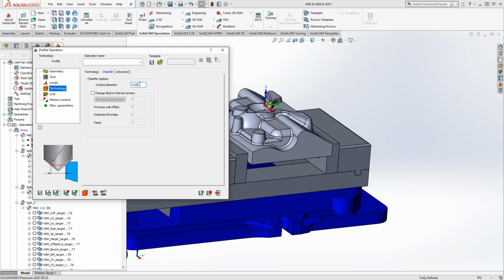If it comes to a single point, it's still looking at the angle of the tip, the angle of that cone shape, and it's finding the cutting diameter along that mathematical cone. So if it comes to a point or it actually is a trimmed cone and has a tip diameter, this setup here for your chamfering doesn't matter. It still looks at just where along that mathematical cone that diameter sits, that height.